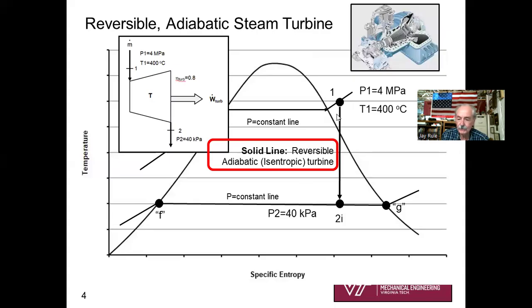That's the indication to yourself and to other engineers that this is a quasi-equilibrium or a reversible process. Now, what's the area under the curve here for this? That's 0. Remember, the area under the curve on a TS diagram is heat transfer. And so you visually see that there's no heat transfer for this isentropic process. Okay, so there you go. There's the setup. You should be kind of familiar with this setup before we get into some definitions here.